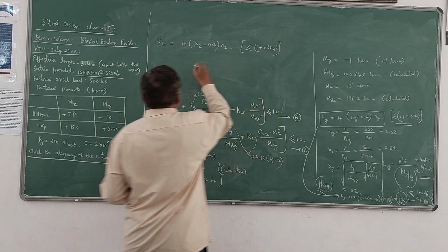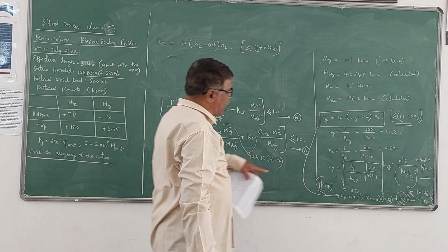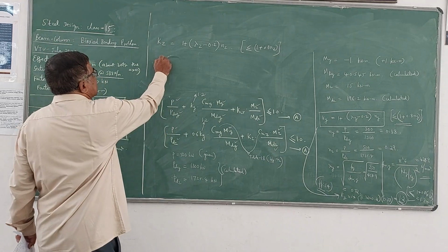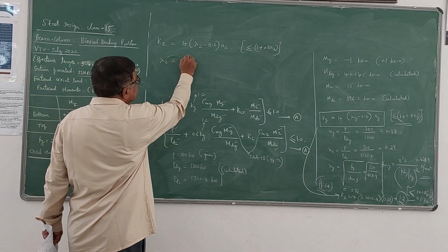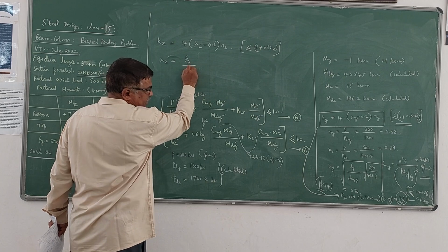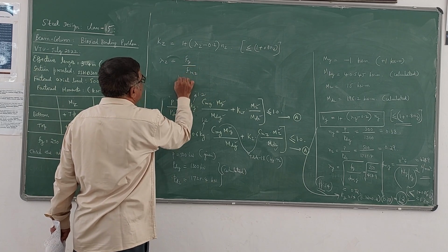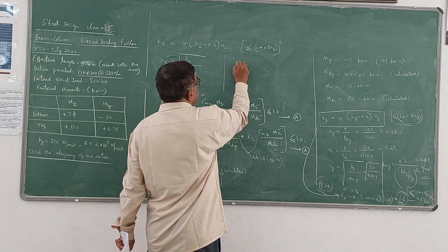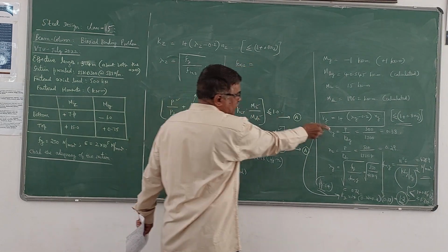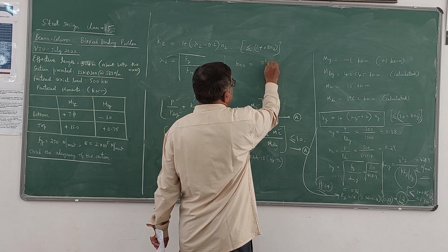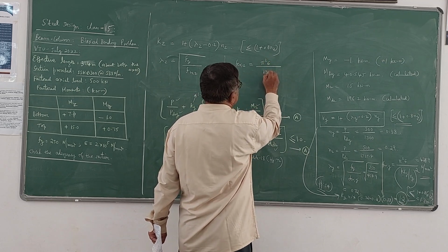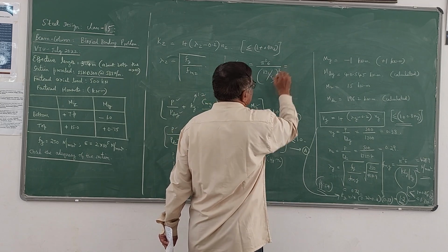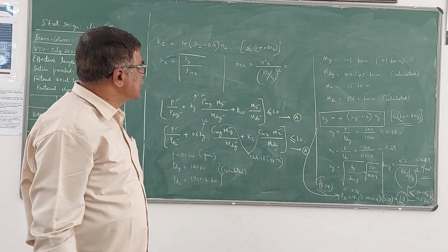Let's check. Now, just how we calculated lambda y, the same procedure is used to calculate lambda z. So lambda z here is under root Fy by FCR z, instead of y we have to take z. So what is this FCR z? FCR z here is similar to pi square E divided by KLz by rz whole square. So here we are taking the slenderness ratio along the z direction.